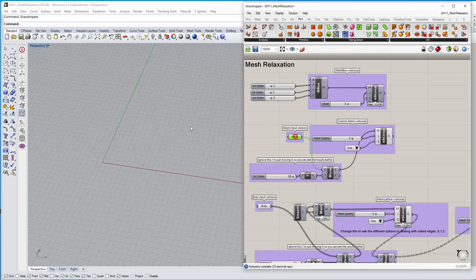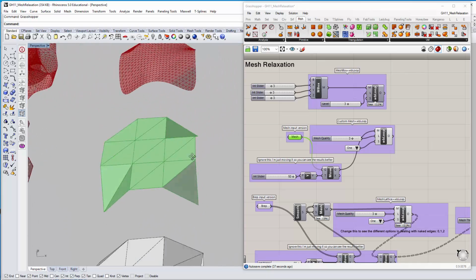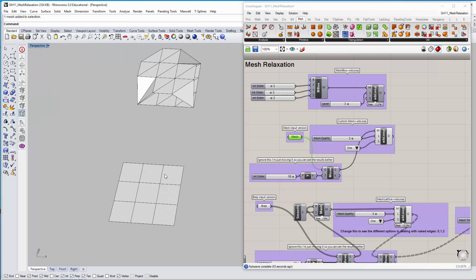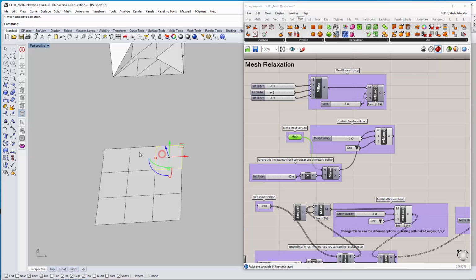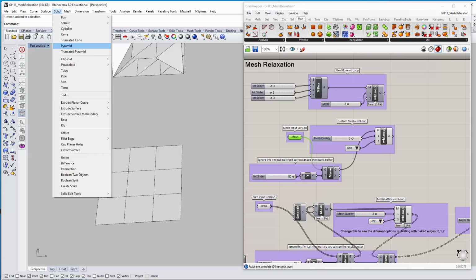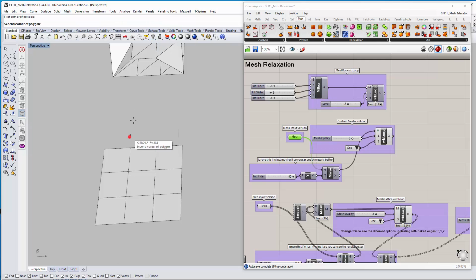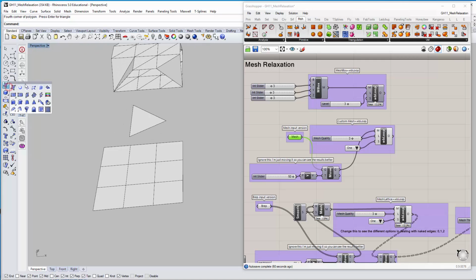Now this is a mesh input. So if you look at these guys, essentially, this was constructed by making a mesh face or a series of mesh faces. You're not probably used to ever drawing mesh faces yourself, but you can actually draw mesh faces for mesh, polygon mesh, mesh plane, mesh box, 3D face, which is basically the same as the 3-point plane tool that you sometimes use a lot here. And it can do 4-sided ones as well.